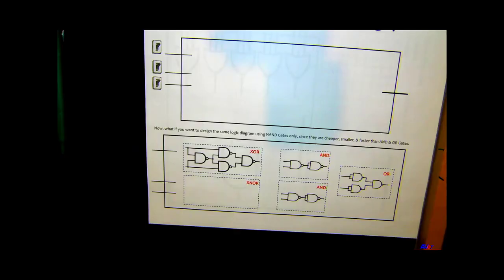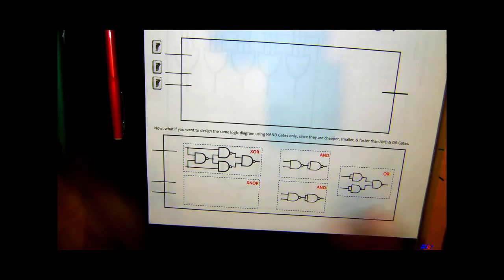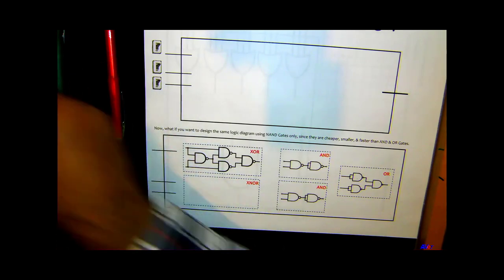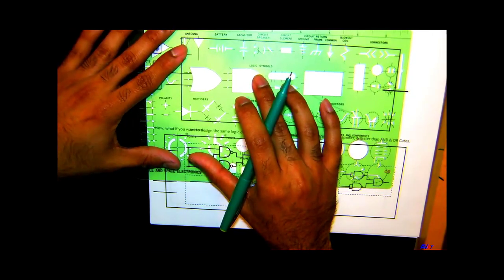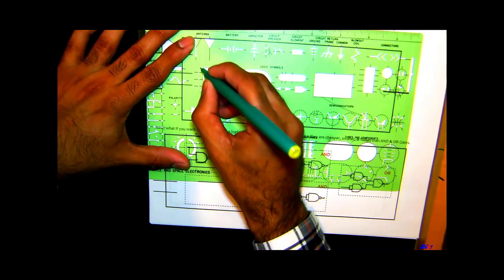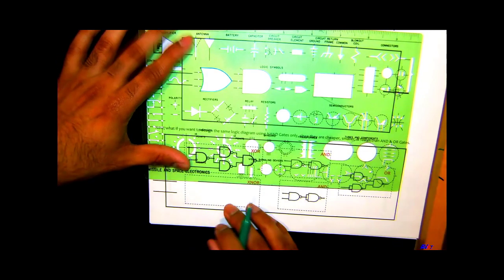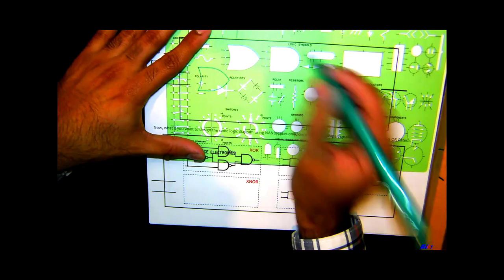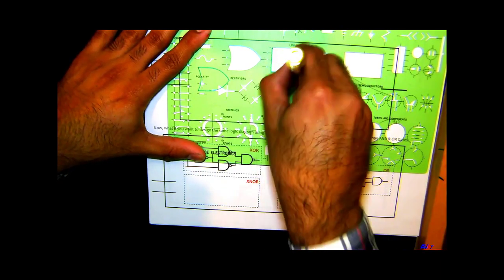Okay, so I have written the equation right here. It's the same equation that we drew from the previous page. And now we are going to draw the combinational logic diagram and implement it. So I'm going to work on this exclusive OR gate first. Say this is exclusive OR, and then I'm going to have this AND gate right here.